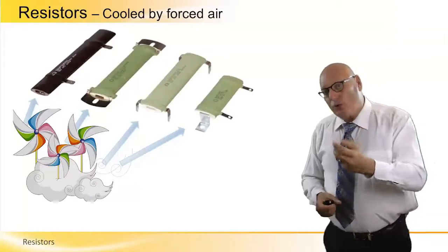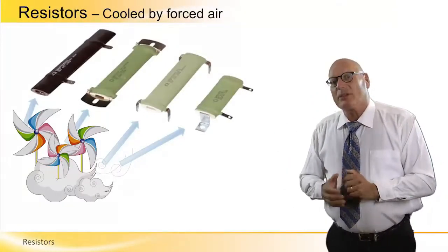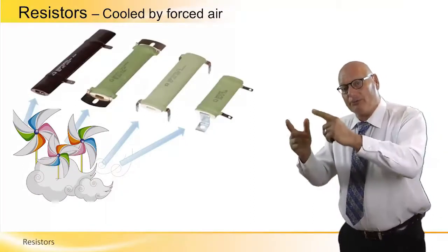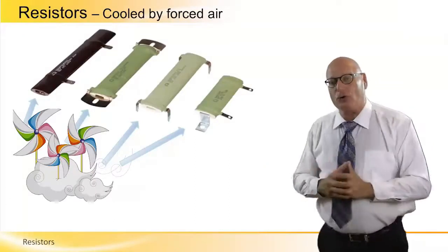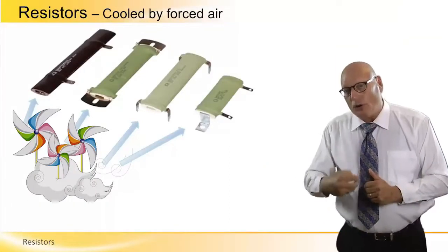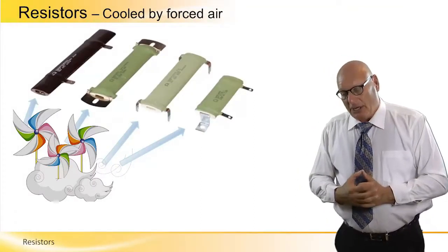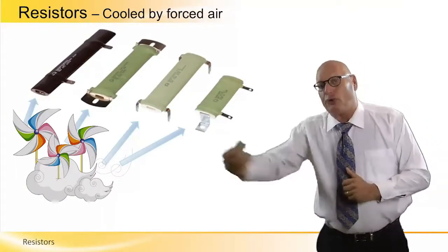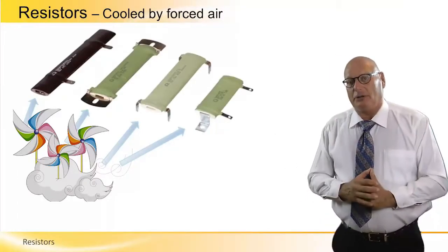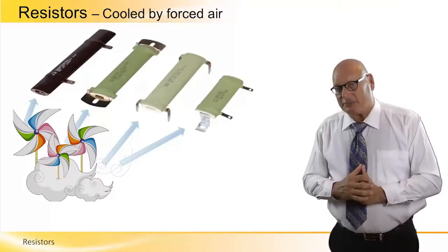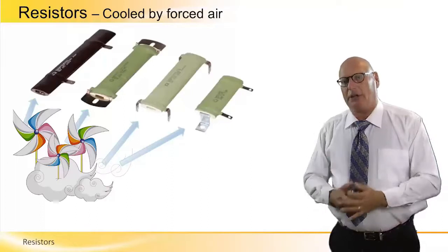And if we continue one additional minute on these ceramic high power resistors, some of them, for even higher power, have holes inside to let the air go through, cool the resistor down, take all this heat and force it out. So eliminating heat pockets inside. And this is an excellent idea specifically for very high power electrical applications.